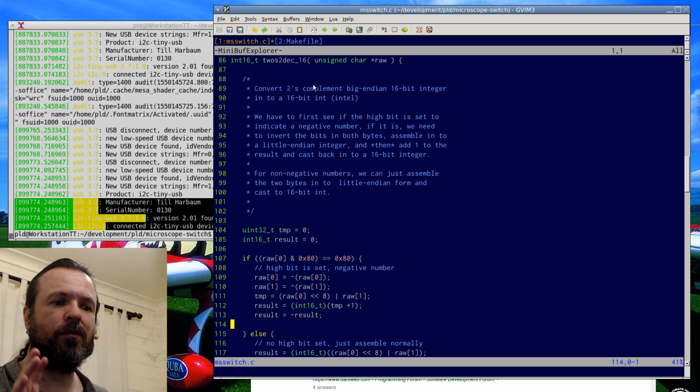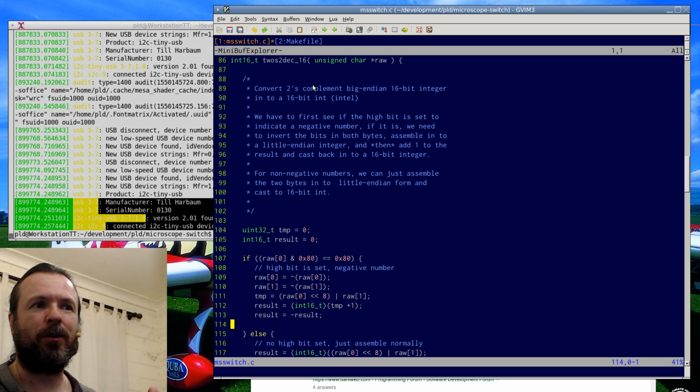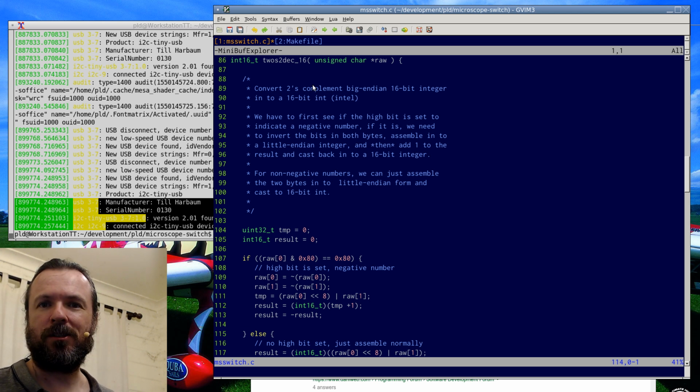Mostly because all of these devices tend to use big endian format, so your most significant byte is first, then as you read the data it gets to the least significant, whereas Intel chipsets use the least significant byte first, and so you can just swap it around, and that normally isn't a problem, except that we're also doing the 2's complement formatting of the numbers, which means you've got to do a bit of bit bashing, and if you don't do that in the right sequence, you just get gibberish data out.